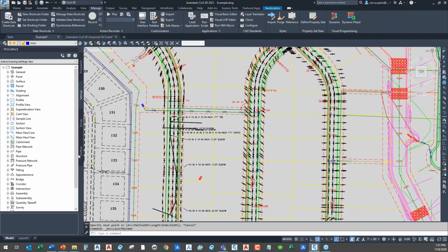Okay, and I have one more question from Ariel or Ariella. I'm not sure if I'm pronouncing that correctly. With style references, can you link multiple template files? Can I connect a master to road, utility, landscape type templates? Yes, absolutely. The idea is that if you're using multiple templates and you only want to have 10 or 15 Civil 3D styles in your road template and 10 in your landscape and 10 in your utility plan, you can keep one master DWT template and then reference from one drawing template to another drawing template. Okay, so that's the big structure and setup there.